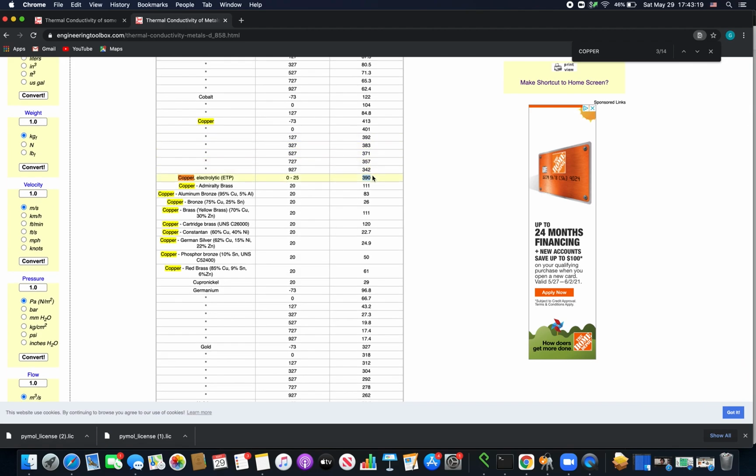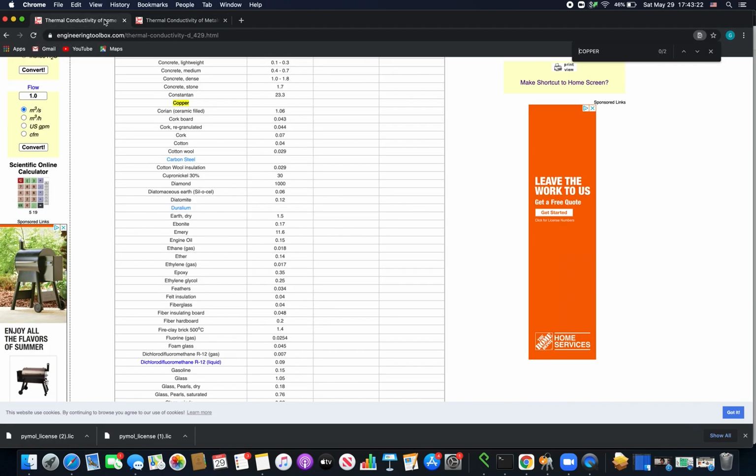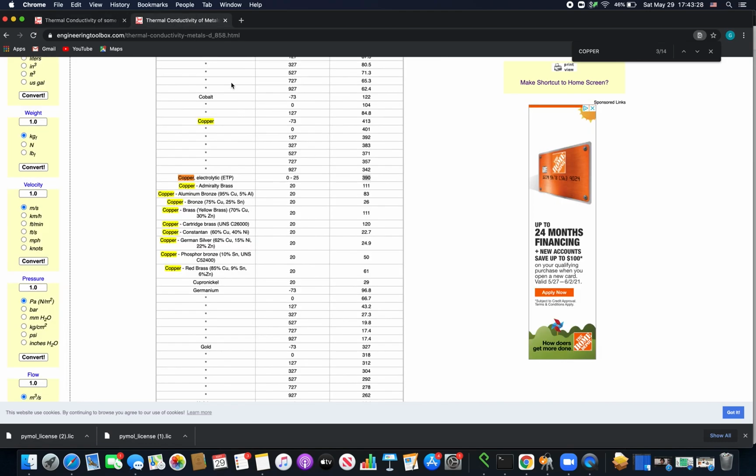So if you mix a lot of copper nanoparticles into this, and you can get over 60% of this being copper nanoparticles, you can get a ton of heat conduction, a ton more than air could ever do, and make it a ton more even. And you would have to coat these copper nanoparticles with a thin layer of a polymer of some sort, which has repeated linked chains. You can do that with graphitization, where you coat it with carbon, which is even more conductive, but it won't be a very big thing because that'll be such a thin layer.